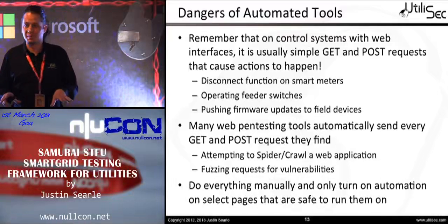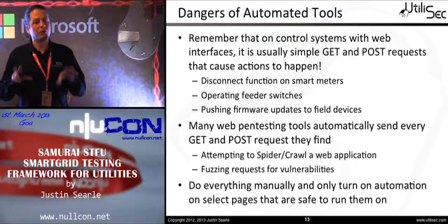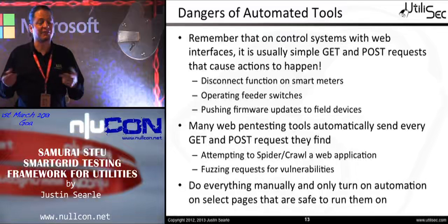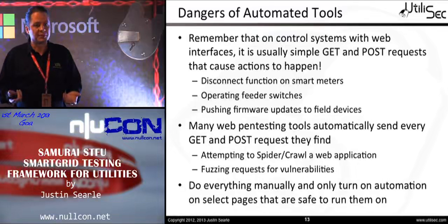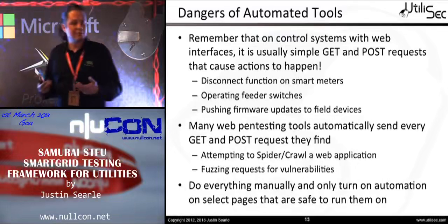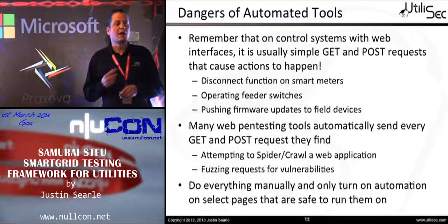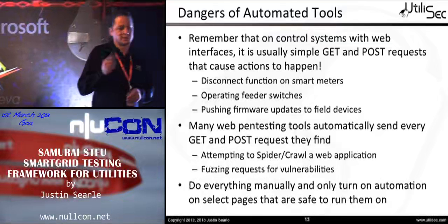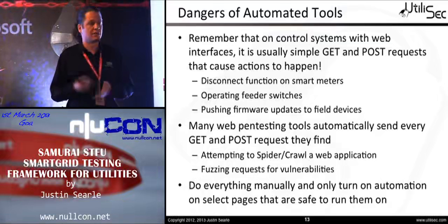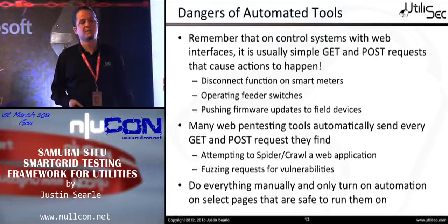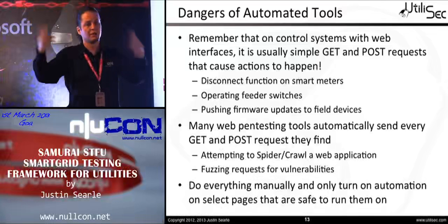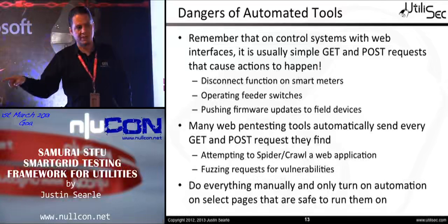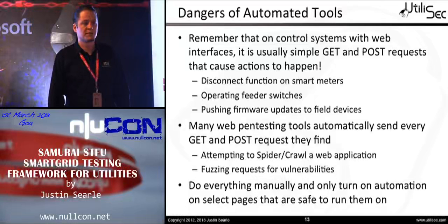Most of our control systems now have human-machine interfaces, basically a fancy way of saying user interfaces, that are now web-based. So we need to test a lot of these web interfaces. However, as web pen testers, if you use your normal routines and kick off your spiders to start spidering, and kick off your automated vulnerability scanners to find the vulnerabilities so you can start reading those while you're doing your manual pen testing, you'll crash all those systems.